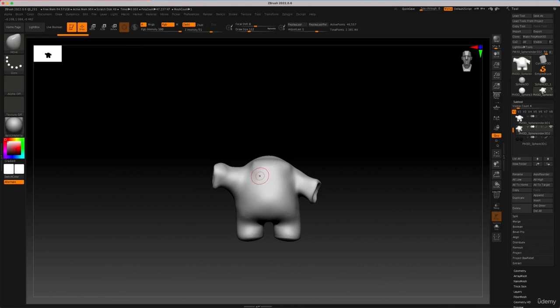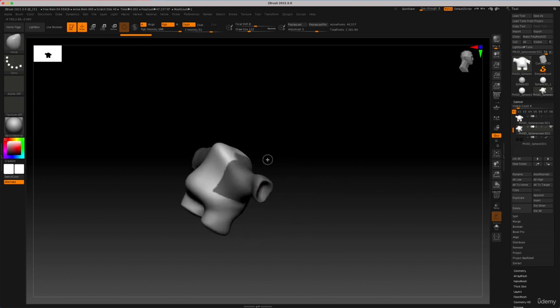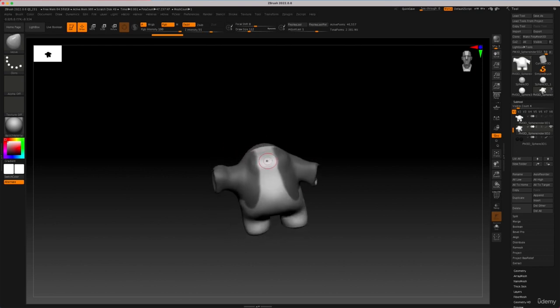Now, from this point on, I want you to toggle back and forth with the X key, turning on symmetry, and hold down Control and simply carve out a jacket. Even I like to hold Control, drag, and do a marquee for these back areas here. You're just looking for a carve out of a jacket. It's basically the only thing we're doing here. So just take your time.